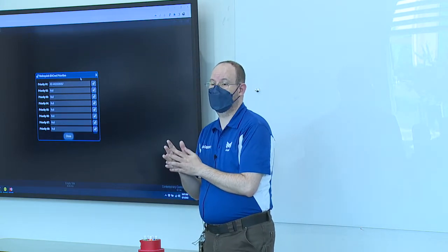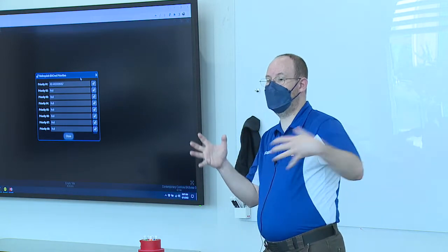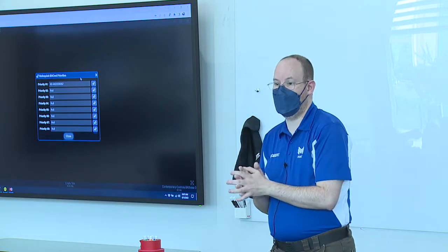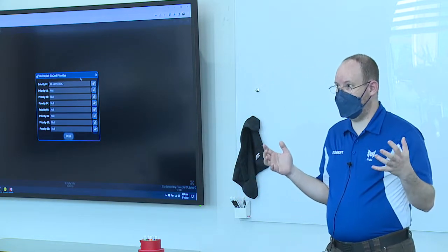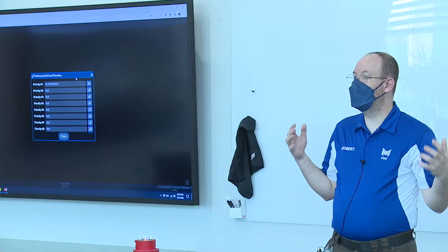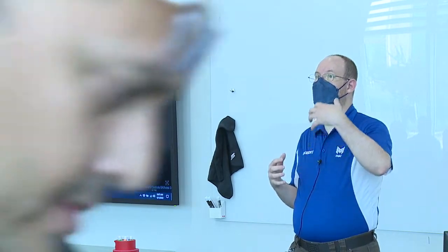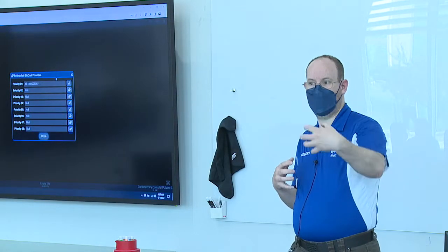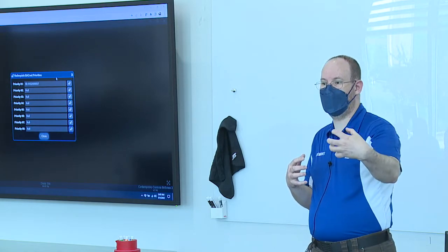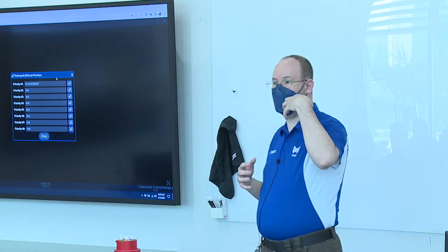So this priority is associated with that point. Correct, yes. It is built into the BACnet object, and it is present in most of the data points, like measurement types or outputs or things like that. It is built into all of those types of BACnet points.